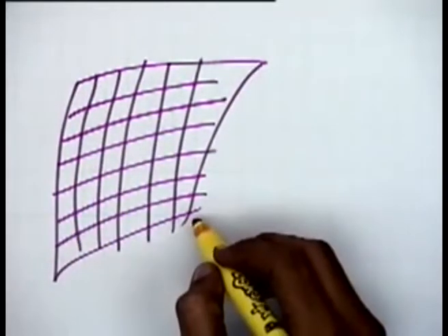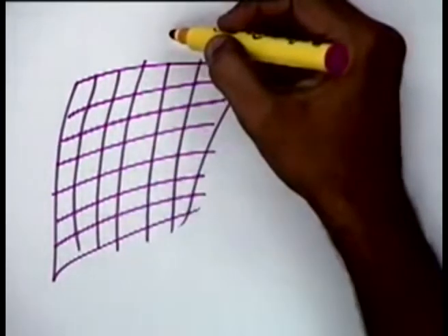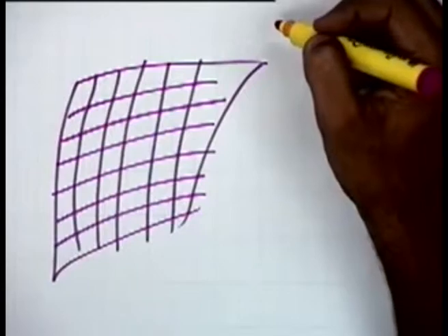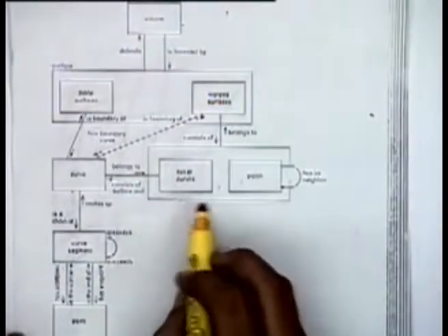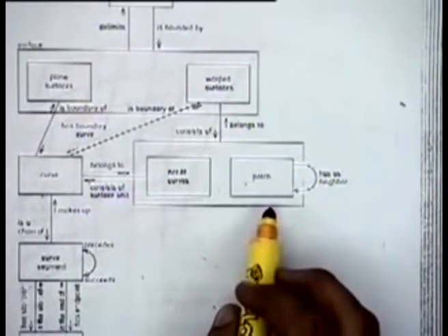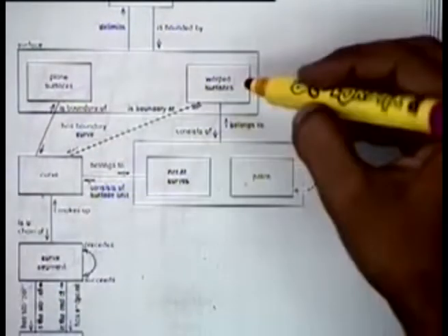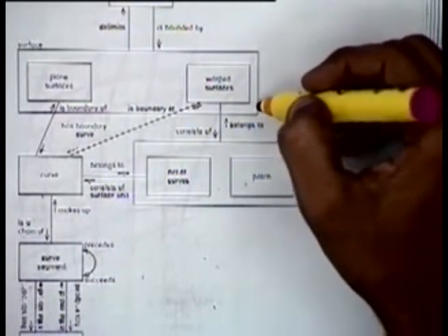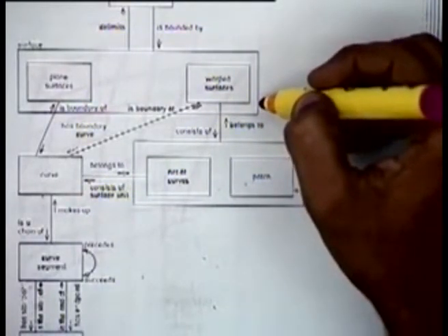One set of maybe cubic curves in one direction, another set of cubic curves in the second direction, and this defines a surface patch. So we can have a network of curves, or patches, which can define a warped surface, or a three-dimensional surface.